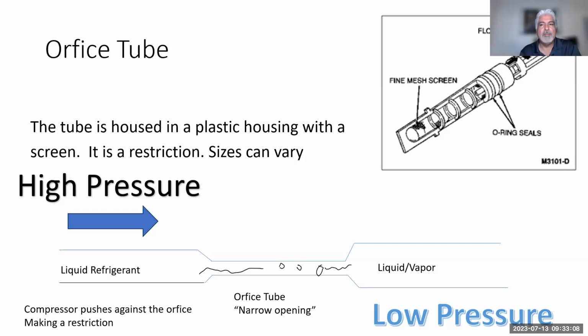You could do that, but obviously I'm of the opinion that you should use the correct orifice tube for the correct vehicle. But again, that's a quick cheat method, because anytime you raise the high side pressure very high, you're now compromising the life of the compressor. The life of the compressor is based obviously on oiling and proper charge and no air, no contamination, but it's also based on how we try to keep that high side pressure as low as possible. Now it's going to run hot when it gets very hot. In other words, like this week here, it's getting over 115. Yeah, it's normal to get high side to see a whole bunch, but it is going to be able to cool very, very well. But at the same time, that compressor is working much warmer. So therefore, definitely oiling is a big deal.